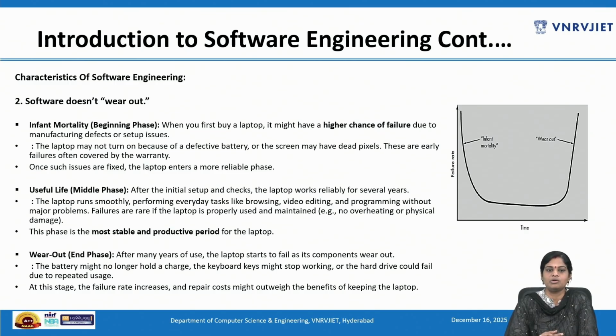The next is the normal life section. We can also call this the useful life period or steady state operation. To understand in detail, the failures usually occur due to overloading, hidden faults, etc. Failure occurrence generally depends upon the function and condition of the particular asset. Therefore, for different assets, the failure rate can be different. The failure rate is almost constant in this phase, and the failure generally occurs due to random events.